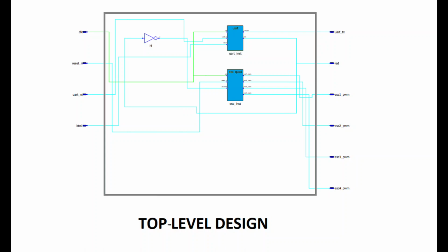So then my top level design here for the HDL module, there's 4 input signals and there's 6 output signals, but my top level module contains 2 submodules. In this case, the clock essentially synchronizes all operations within this, I will call it flag controller. Then the reset signal will restart the system.